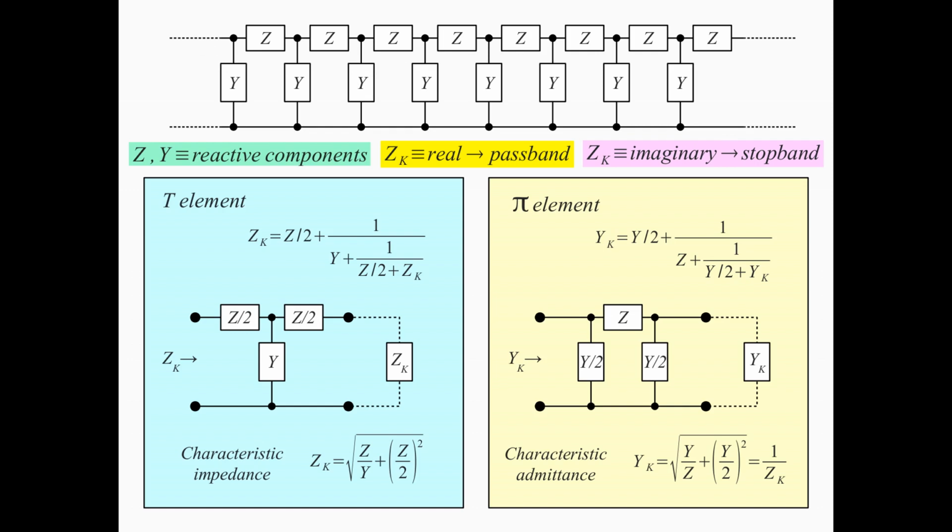This is a little bit different from the transmission lines we already talked about in this course. With transmission lines, we had infinitesimally small components Z and Y, and we can calculate that for infinitesimally short sections of transmission lines. While in filters, these sections have to have finite dimensions, finite values.